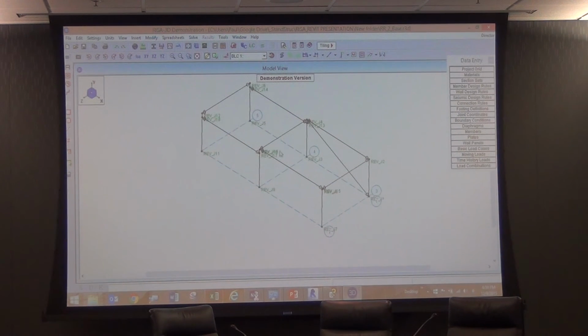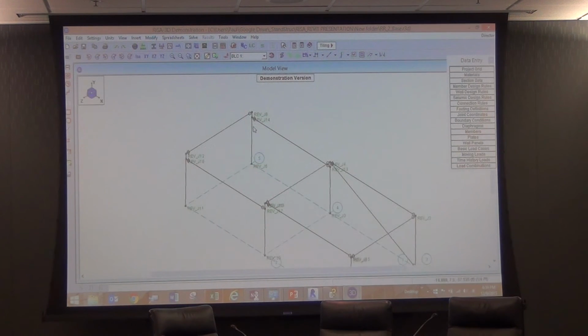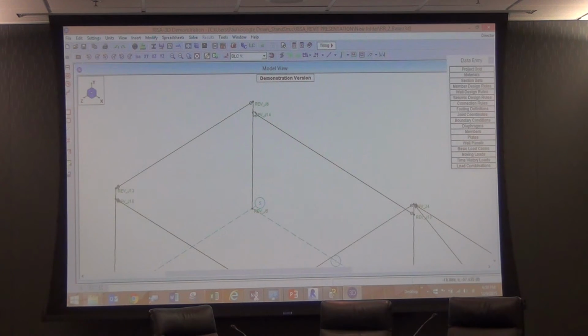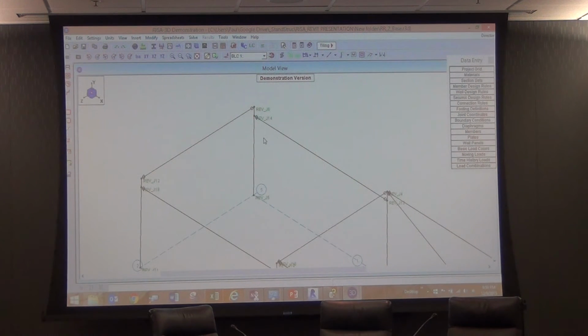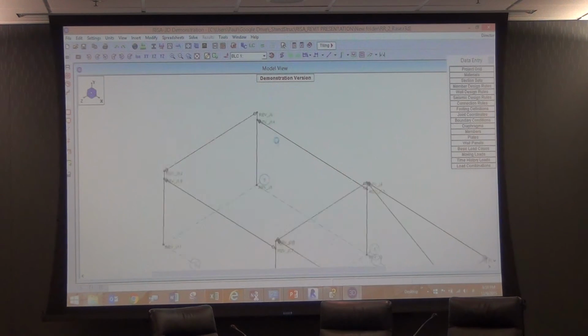I didn't show, but if this would have been that model that I had previously, these columns would be off those grid lines and things would not be lining up right. They wouldn't be connected. And in fact, I had a problem even when I pulled this in where it didn't even recognize that there was a connection between those two when I didn't have it set to be at that projection line. When it was set to auto detect, it screwed a bunch of stuff up.